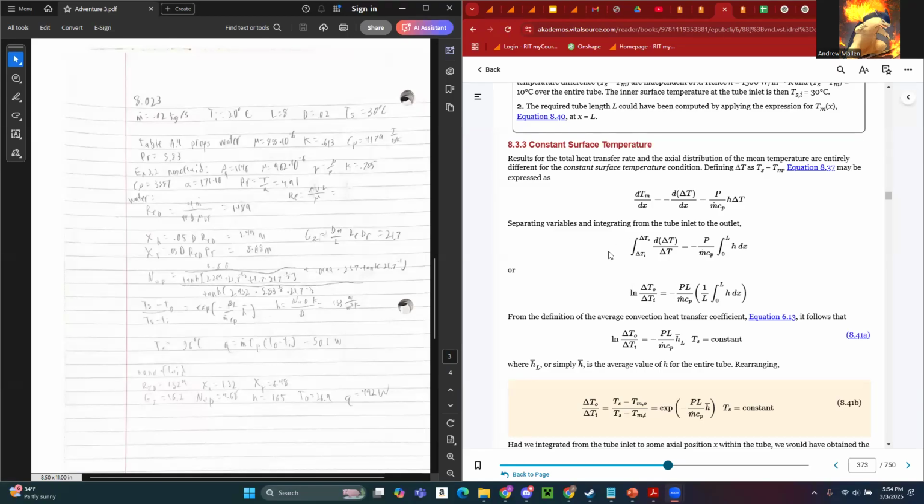Now, it can seem kind of weird that the heat flow in the nanofluid is less than that of the water, even though it rose to a greater temperature. That's understandable considering that the water just has a higher specific heat and therefore has a higher thermal mass. It takes more energy to heat up the water than the nanofluid.